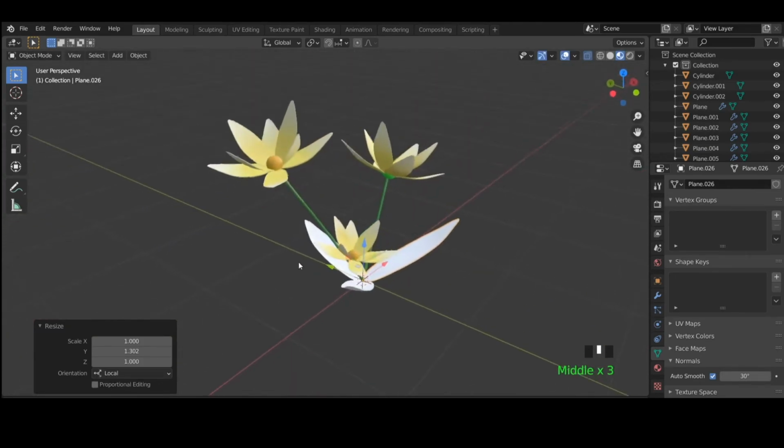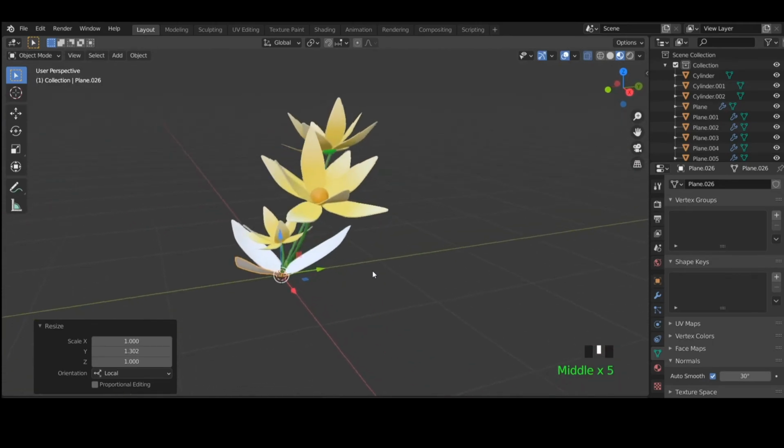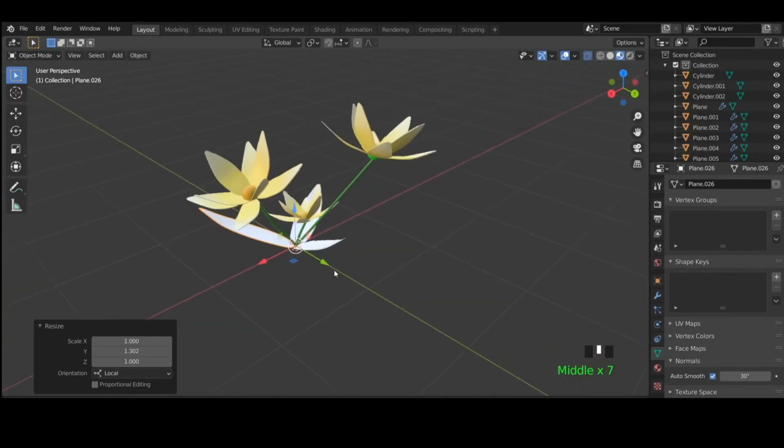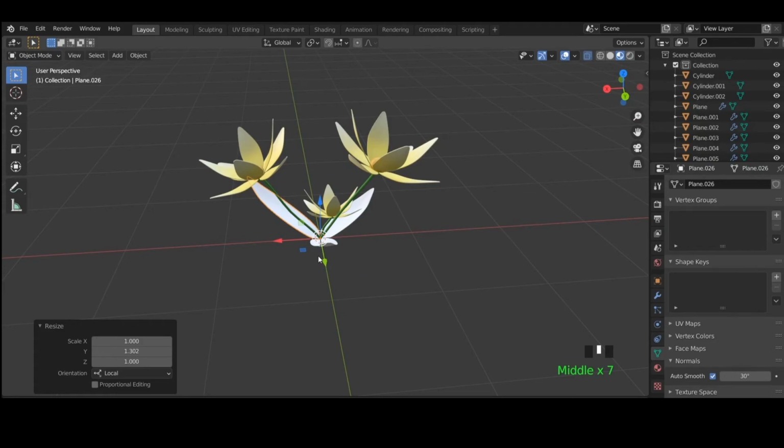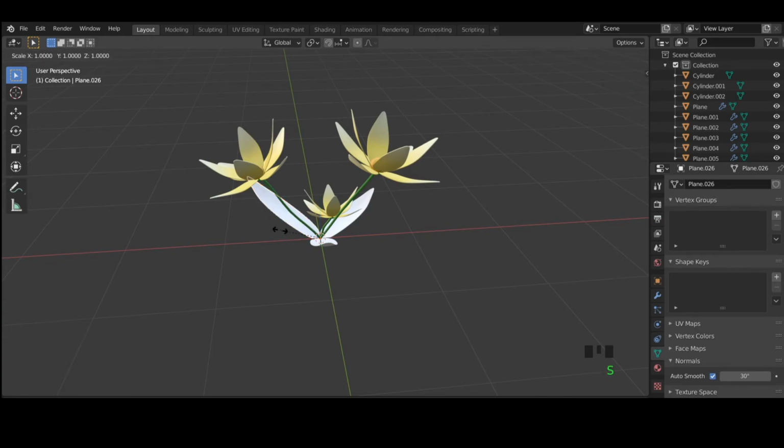If you press Y 2 times, you are scaling or doing that operation along its local axis. So the global Y is along this line because I'm selecting global here. Global is along this line, but if you say scale Y, it is scaling along the other. Now it's local Y.